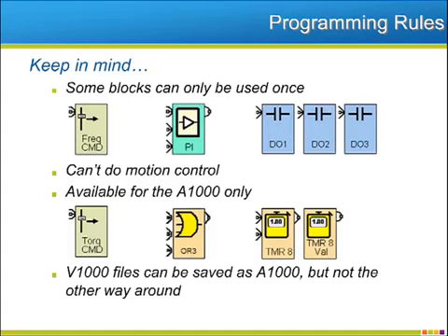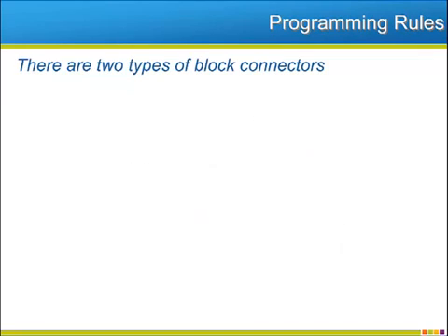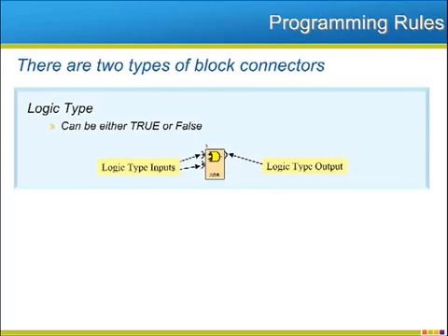Once you have downloaded the DrivesWorksEZ program to the drive, you should not initialize the drive. Doing so will cause the DrivesWorksEZ program to behave in unexpected ways. No matter how many connectors a block might have, there are only two types, logic and numeric. Logic blocks have only two states, true or false, on or off, 1 or 0.